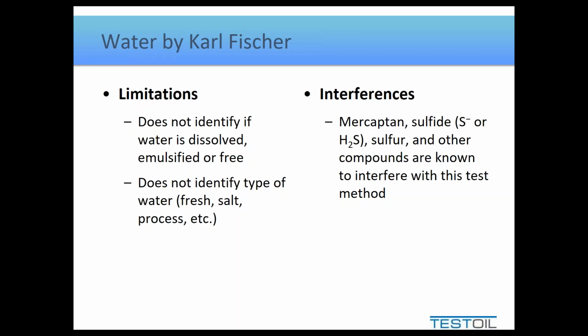Now, the interferences to this test, just so you know, are anything sulfur-related. Those can skew the test a little bit. So if we have a sour application, understand our water content by Karl Fischer may not be as accurate as we would hope for, but still, if you're trending it, you get an overall feeling if the water content is increasing.